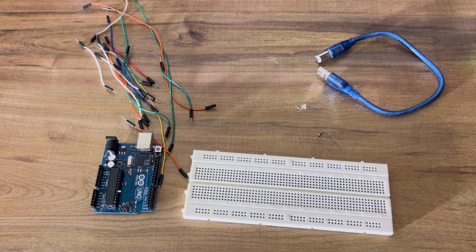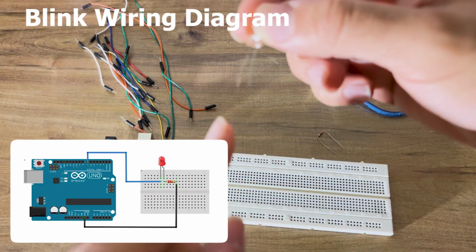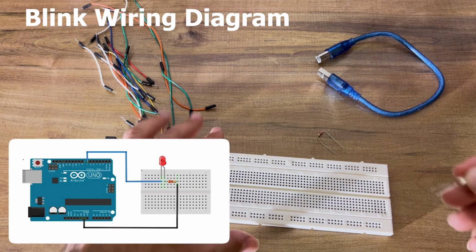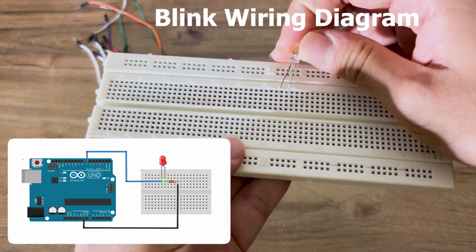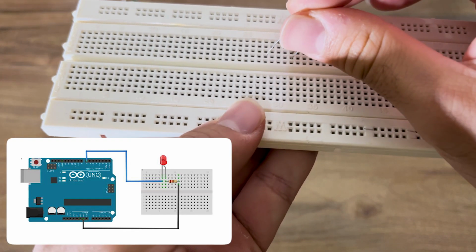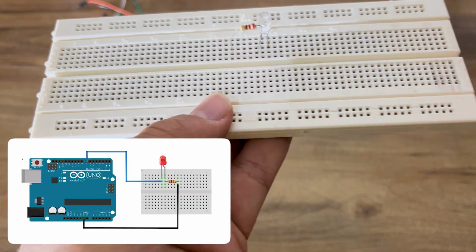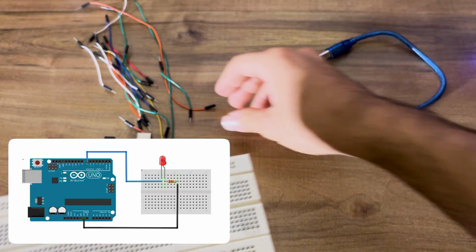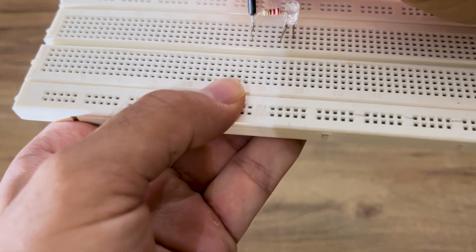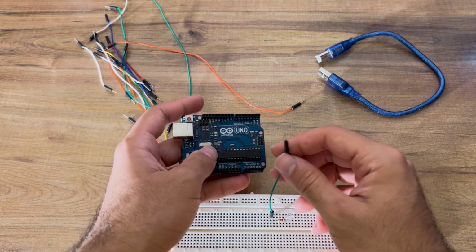Okay guys, as you can see in the picture, this pin is anode pin and this pin is cathode pin. So I have to connect anode pin to resistor pin, as you can see here. Okay, so anode pin connects to resistor pin, and from another pin of resistor I connect to digital pin from Arduino, pin 7.